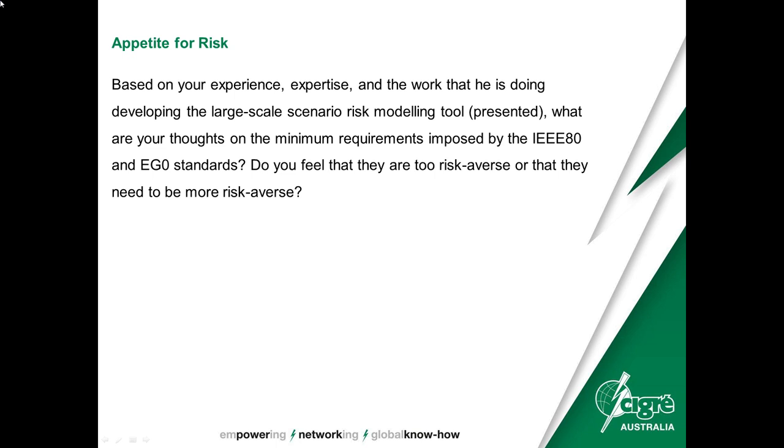In Australia, the IEEE 80 criteria were replicated in EG1, which is quite a good document. They were used for a long time in Australian Standard 2067. They were what most of our assets were built on for a long, long time. Those voltages were applied almost independently of where the voltage occurred, what people would be in the area, how often faults occur, and all these kinds of things. But on average, they weren't too bad.